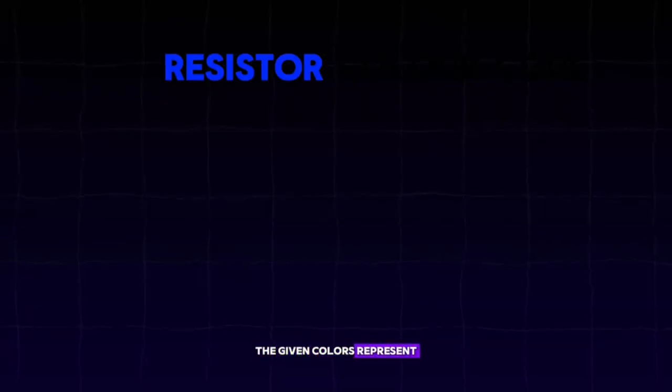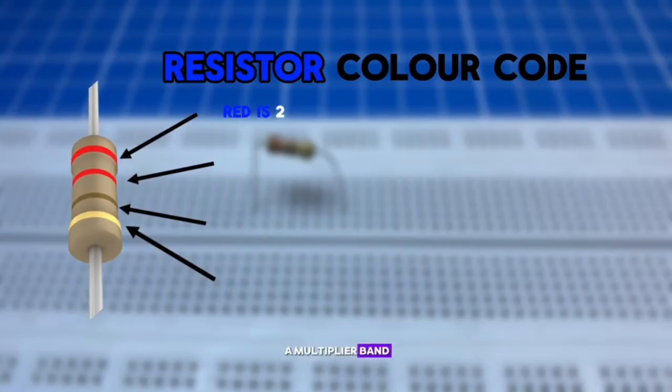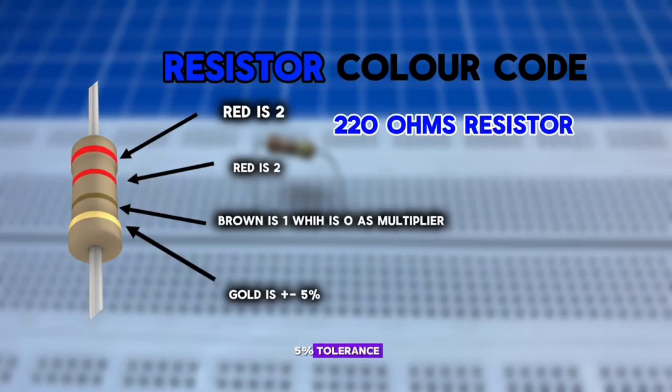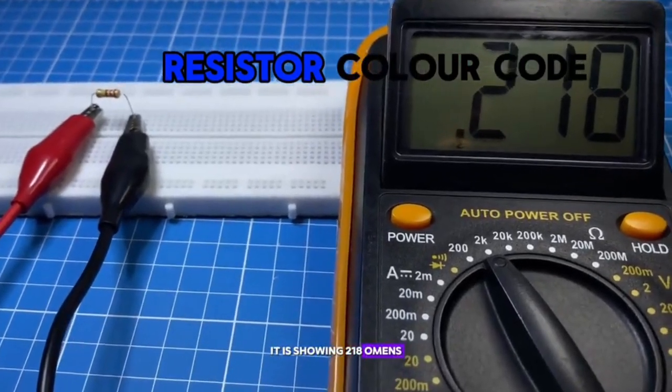The given colors represent digit 2, which is red, and the second is also 2, which is also red. The third band is a multiplier band. However, the color brown represents a multiplier factor, and brown is 1, which is 0 in multiplier. The last band represents the tolerance level, which is plus or minus 5%. So in this case, the resistance value of this resistor is 220 ohms, with plus or minus 5%, or 0.22 kilo ohms. As you can see on the multimeter, it is showing 218 ohms, which means that 2 ohms is the 5%.